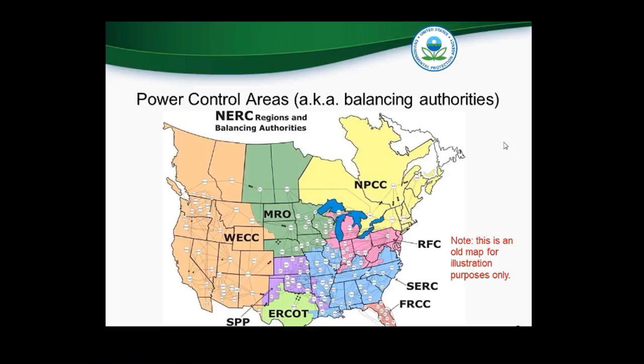Another question is asking about a little bit more elaboration on the distinction between marginal and average emission rates and their appropriate use. Right. Well, the term average gets thrown around a lot, and it could be an average of a whole bunch of things. But generally, we're talking about system mix as akin to an average or a total, where you're looking at the emissions and generation from all of the units in a certain area, including nuclear units and hydro units.